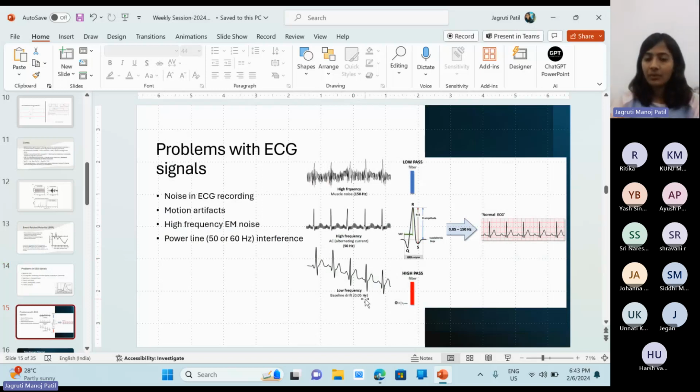So what you need to do is apply different kinds of filters. You need to identify where the particular noise is interfering, what information you need, and then filter it. So this is how there are problems in ECG signals. People have been working on the same. There are LabVIEW models. I did this in my bachelor's: a project on LabVIEW where I acquired the ECG signal with a LabVIEW DAQ system, after which we characterized different kinds of arrhythmias, whether it's a brady, a tachy, a flutter or a fibrillation. We differentiated all these and saw how to do the signal processing, filtering, and acquisition.